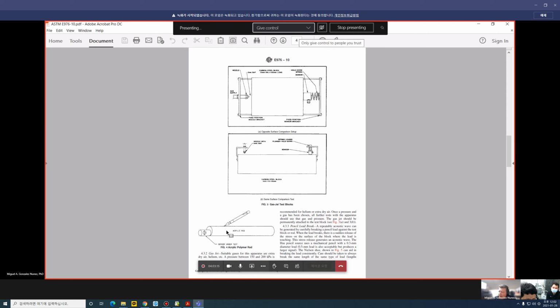And you can tell how bad or how good your dry coupling is compared to this one. All right? And then you do the same when you use the membrane. Use the membrane to mount the sensor on your test specimen and perform 3 pencil breaks 5 centimeters away from the sensor and compare them again to this one and see if the readings are higher or lower.